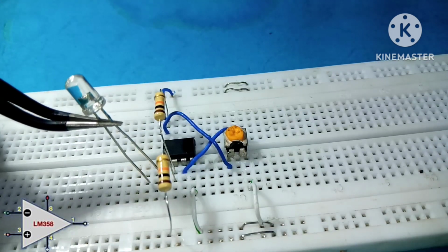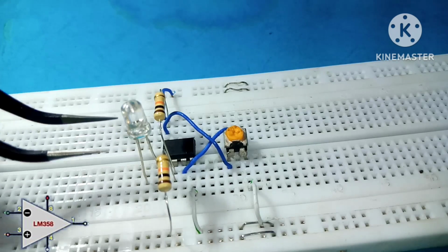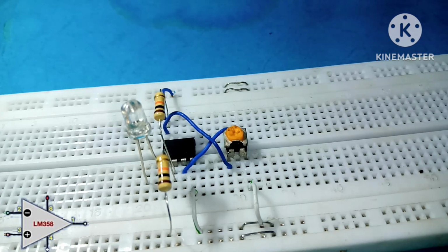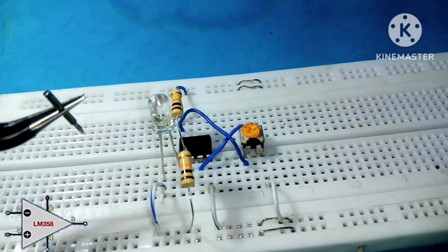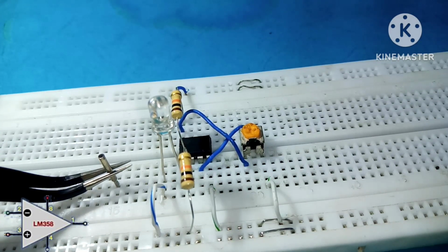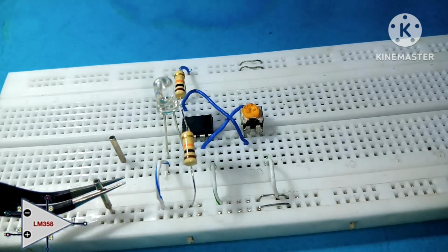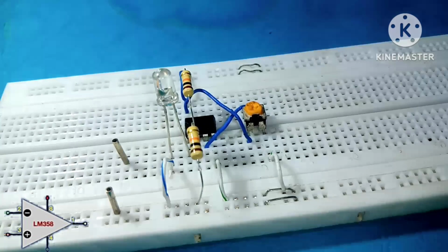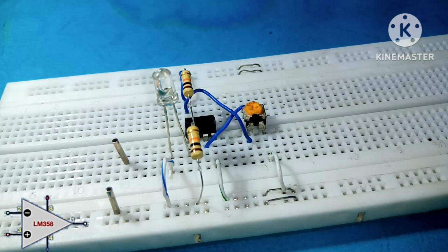Place the LED such that its anode is connected to pin 1 of the IC, and send its cathode to ground. Pin 1 is the output of the op-amp. With these pins, I'm going to be using crocodile clips so we can clip our multimeter clips to this to determine our output voltages each time we vary the signals.